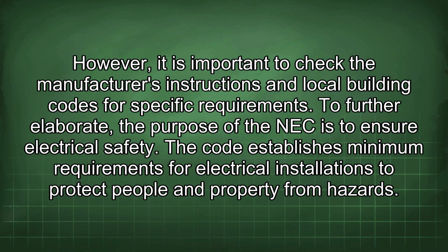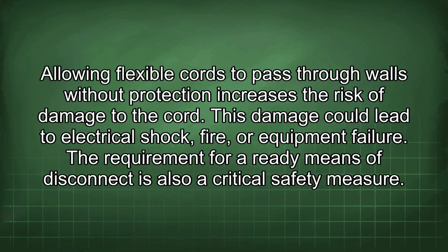To further elaborate, the purpose of the NEC is to ensure electrical safety. The code establishes minimum requirements for electrical installations to protect people and property from hazards. Allowing flexible cords to pass through walls without protection increases the risk of damage to the cord. This damage could lead to electrical shock, fire, or equipment failure.